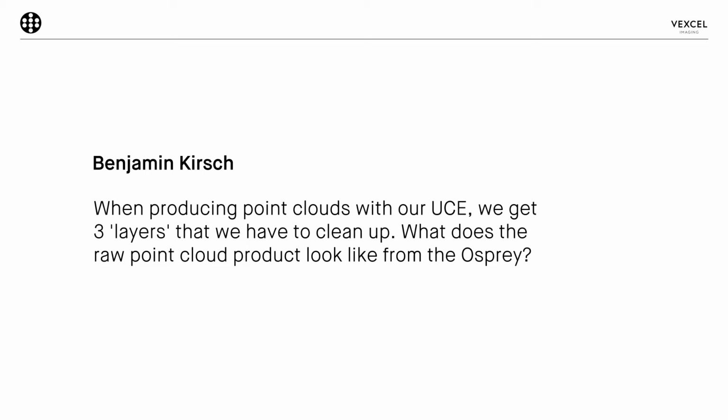That means that this point cloud is richer than the DSM, so it does contain a few points above and below the surface that is finally in the DSM, in the raster data set that you can view and export. So that might need some adjustments or some cleaning before using for some application.